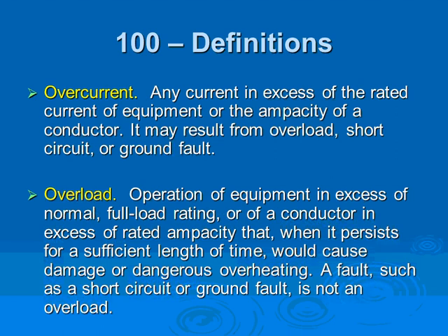So when Kiljic talked yesterday, you guys do motors, right? When he talked about the overload that we add to the motors, this is above and beyond the already existing overload component in the circuit breaker. Because motors are very expensive, very sensitive, so we need extra overload protection. Though the circuit breaker will provide you an overload, we need more above and beyond what the circuit breaker or the fuse provides, so we have a separate overload to protect this equipment.